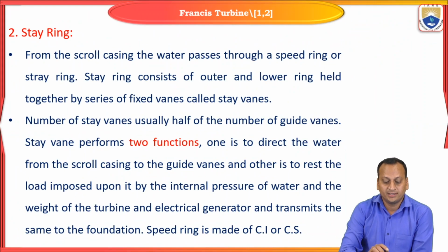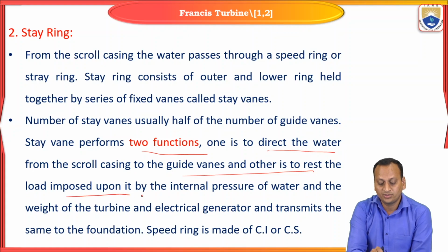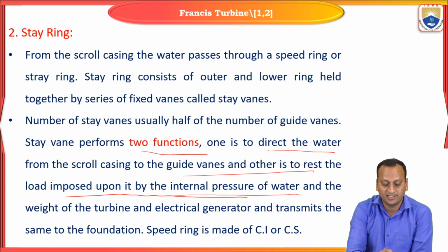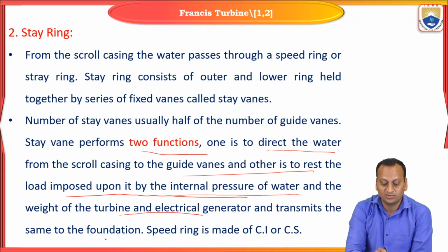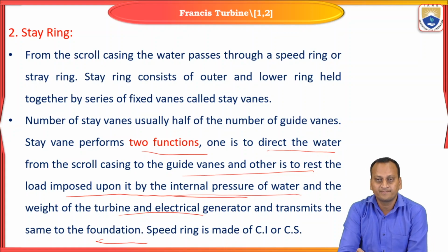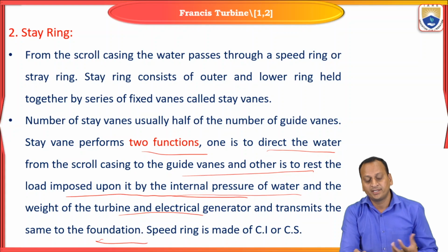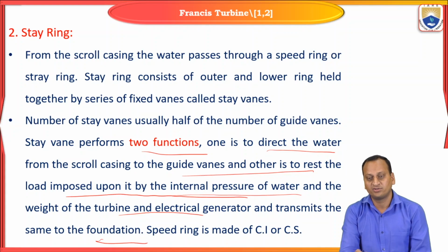Stay vanes. Here the purpose of the stay vanes is twofold. One is to direct the water from the scroll casing. Another is to bear the load imposed upon it: the internal pressure of water and the weight of the turbine, electrical generator and transformer, which is transferred to the foundation. So the inlet water forces coming from the water will be borne by the stay vanes and will be transferred to the foundation.